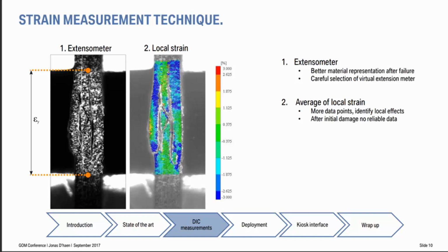So far in 2D, they can only assume that there is buckling, but they will go to 3D and confirm that there is. But they also use the 2-point extensometer because they find that even though there is delamination, the coupon as a whole still has a certain strength, and they want to acknowledge that.